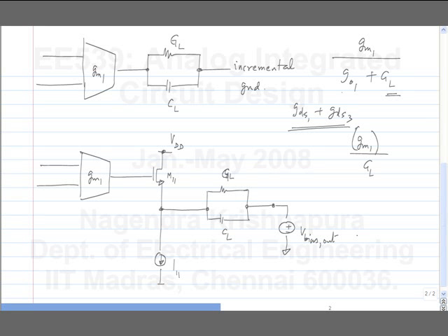What will be the DC gain of this stage? Approximately, what's the DC gain? It's the DC gain of the first stage, right? Let's assume that this is indeed behaving like a voltage buffer, then it's the DC gain of the first stage. We know that, of course, this one won't behave like an ideal buffer. It will have some output resistance. So, DC gain will be smaller than that, but it will still be close to the DC gain of the first stage. What is the potential problem with this?